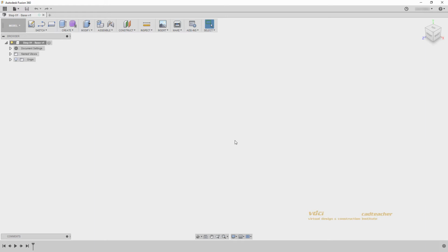You will notice that I have turned off my grid, and that is down here at the bottom under Grid and Snaps. My layout grid is off, and this is for the video to make it more clear. I have also unchecked Snap to Grid and Incremental Move. You may feel free to keep these on, but we have found that it is more clear to record with them off.